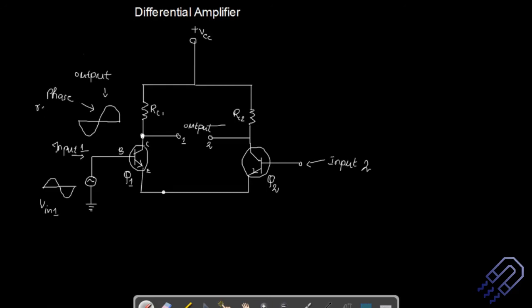So when you write it down or draw it in your copy, I think you should take some space and try to keep all the points in one figure as I'm doing, because in one picture you can get the entire image. On the other hand, if you're just doing it from this part, we need to bias the emitter also. So we can bias the emitter via the resistor. The theory is the same as how transistors work. So this is the biasing of the emitter. So this is minus V EE. So this is R E.